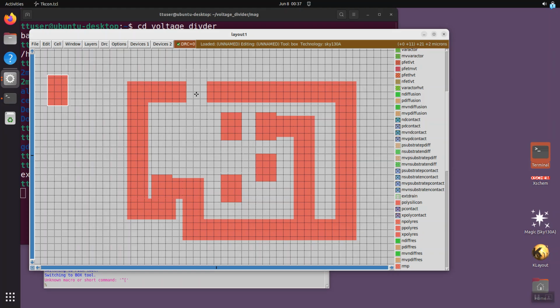Okay, so I didn't erase it. But what happened is, Magic doesn't keep track of the polygons, it keeps track of tiles, like stitches. And so by having this, what you might think of as a weird behavior, allows the design rule checking to happen in real time. So let me do that again. I'll do a move. I'm trying to move that.